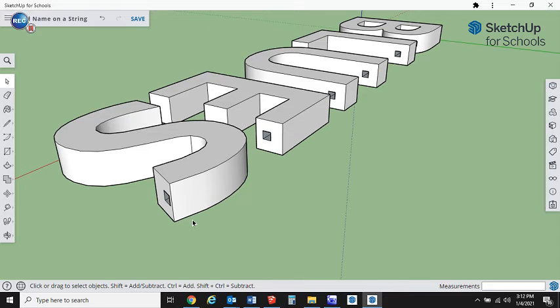Manifold means that it is watertight, and it's necessary for printing. It means that your model is completely closed with all the outside faces facing out. And you'll notice that these have different colors. This one's a little bit more shaded in the inside, right? Whereas the outside colors are white. Okay, so we're going to try to change that so it's easy to see. We're going to basically flip some of these over so that the other side is facing out. If it's a little bit confusing, it'll be more clear here in a minute.